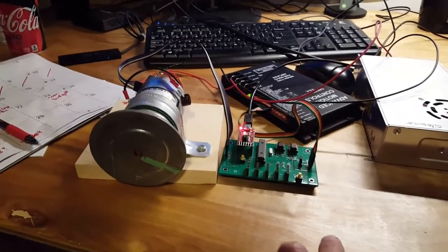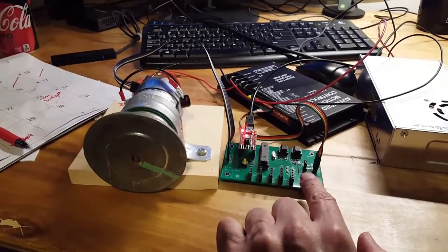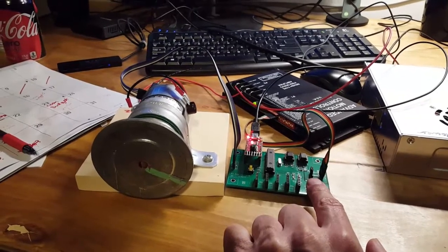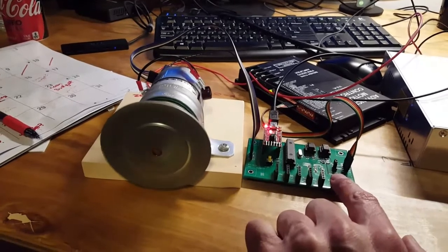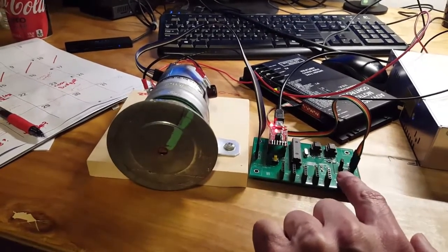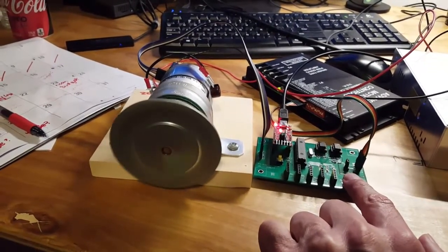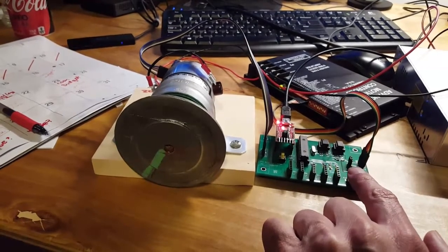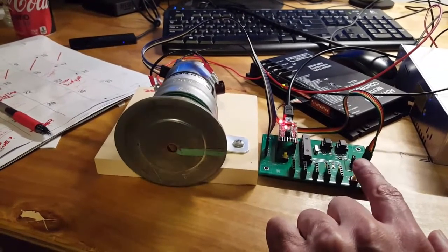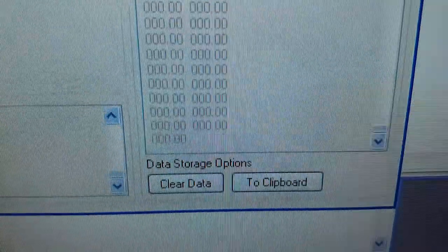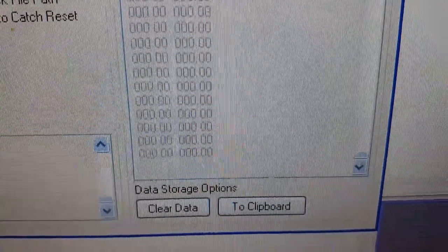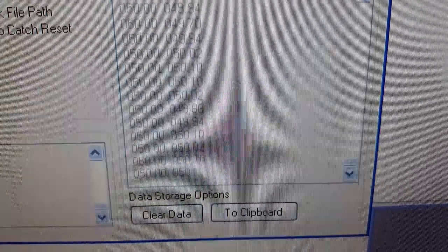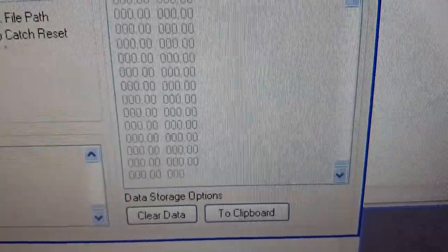Here's an example of digital PI control. I've canceled the pole at -6 in the S-plane and placed it at 0.6 in the Z-plane. And notice it is extremely responsive. It's either going 50 or 0 radians per second. You can see that on display. The first column is the set point. The second column is the actual speed. Gets there really, really fast.